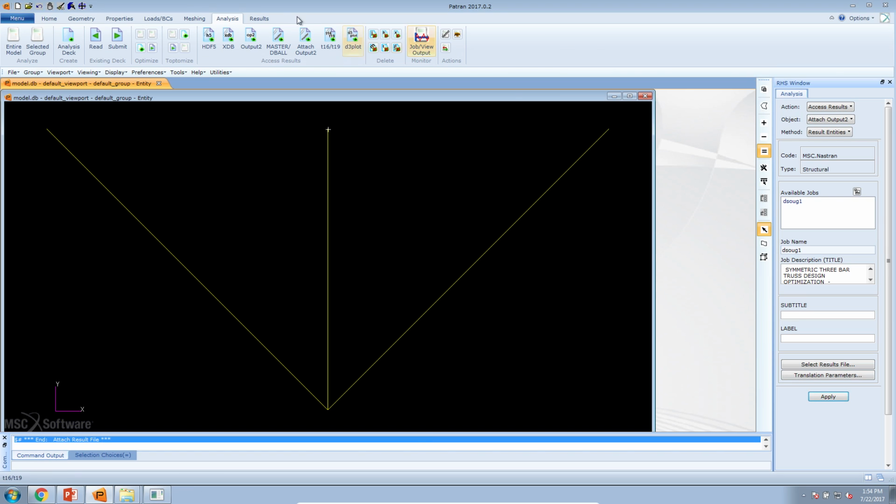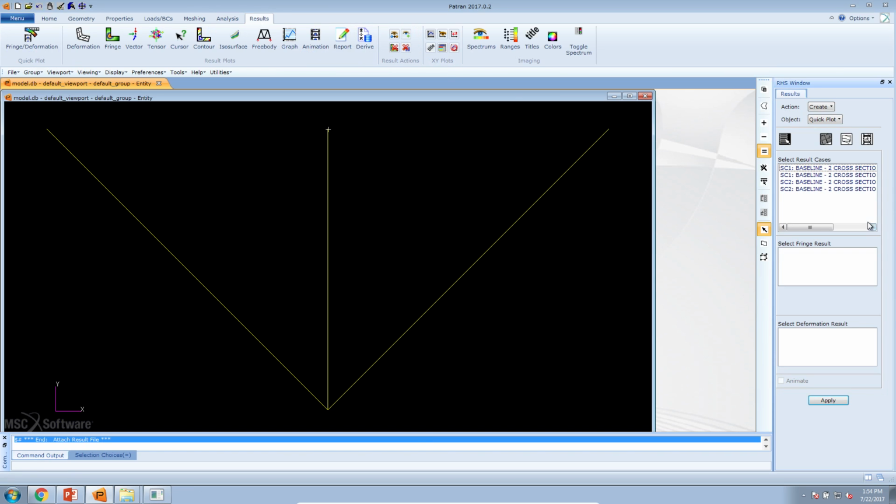And when you look at the results, you notice that we have 4 results. The reason we have 2 results is as follows. 2 of these results are for the very initial original model. Remember, we had 2 subcases. One good indicator to tell you that this is the initial design, if you look here, at the very end, there are these markers, D0 and D7.